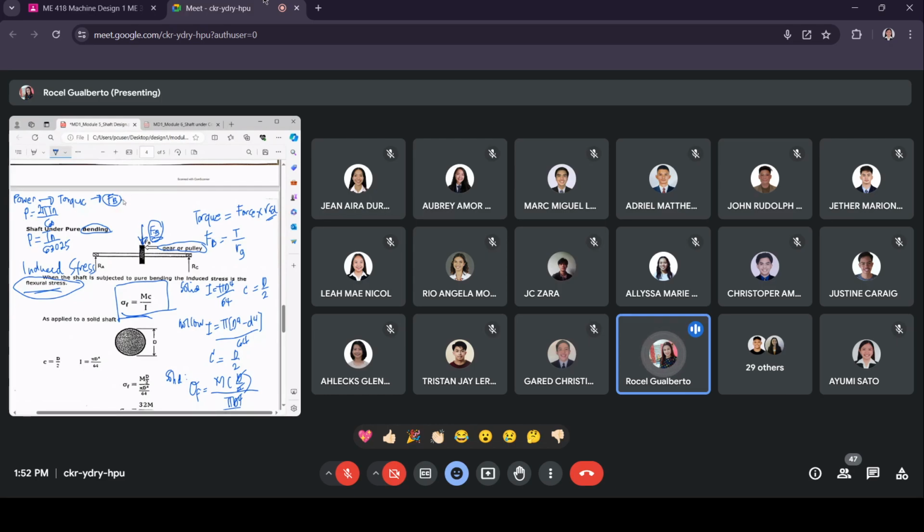And from the bending load, you have now the maximum moment, using table 82 on page 2, or you can create your shear and moment diagram to obtain M maximum, to be used on our equations for the stresses.